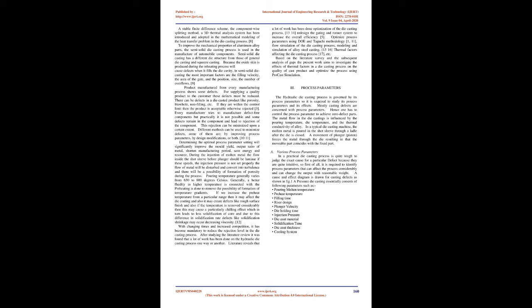The current rejection level in casting is around 11 to 13%, so attempts are being made to bring and keep the rejections in the die casting process within the 6 sigma limit. Various defects such as porosity, blowhole, improper filling time, hot spots, and misruns in the castings were properly studied. Analysis and optimization of the preheating temperature of the mold were performed with the help of ProCast Simulation software.